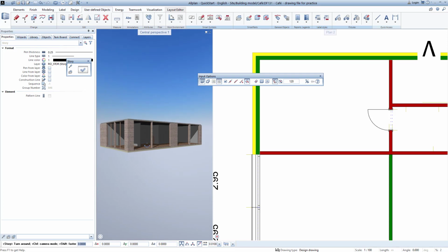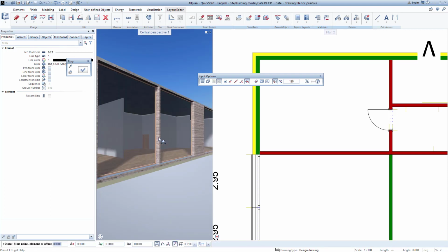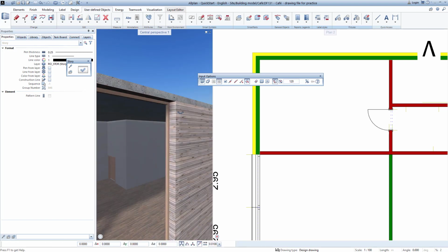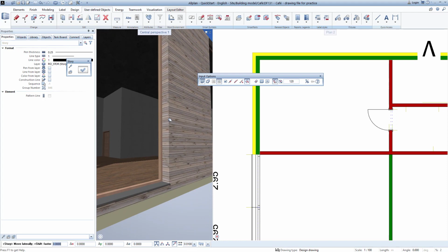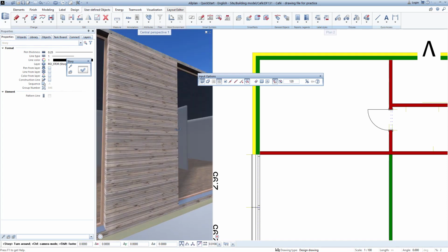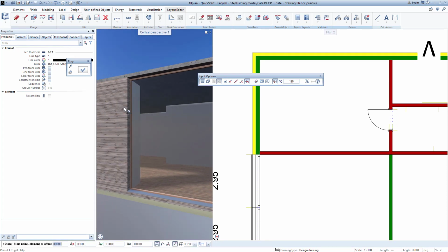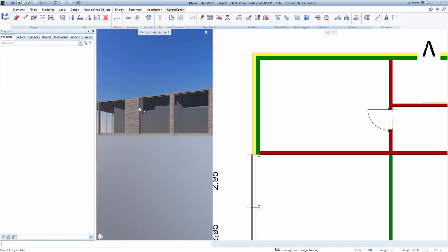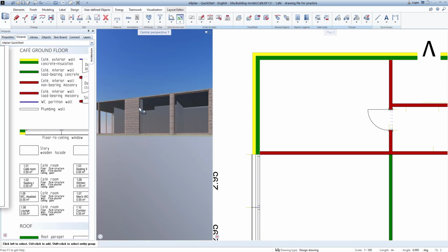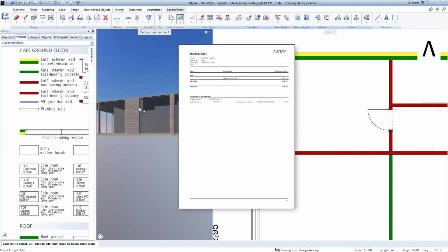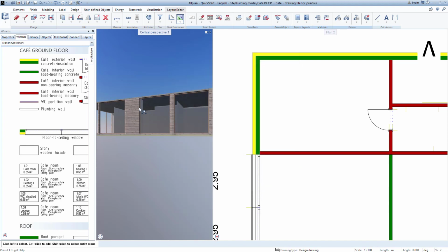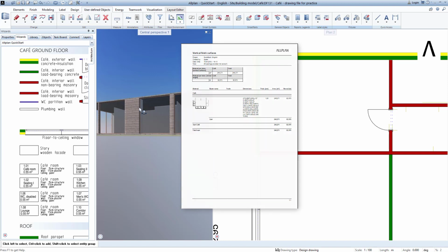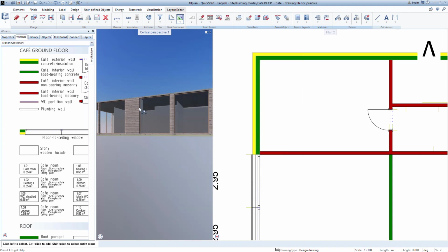With this method, Allplan has found this outline of the building itself, and this also works well with complex geometries. In the animation, you can see that the facade completely encloses the building, each window and door opening is automatically detected and is created from the outside down to the respective smart part. I use this story component for three things. Firstly, I can create the gross area content calculation with a report at any time with an Allplan story at the press of a button. Secondly, I can calculate the area of the facade up to the correct analysis of soffit surfaces, and in this example, it also gives me my facade preview.